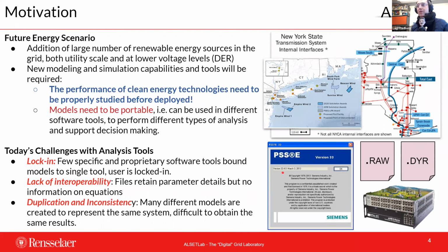The current situation, for example, when we were working on NYPA, is that most of their work for planning models is done using PSS/E. However, they have a real-time digital simulator, and when you build the models and compare them to each other, they're nowhere near. And this is not really a problem of the tools per se, but the fact of how we have been building this for years without really understanding the consequences of what it is going to affect in our capability to do things.